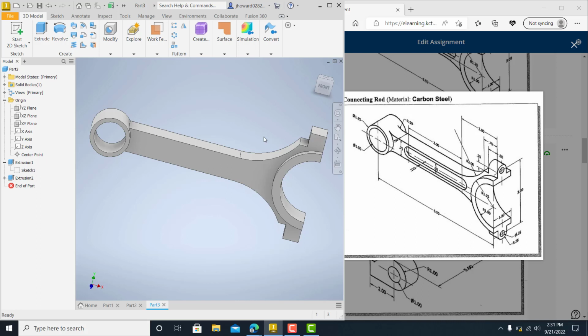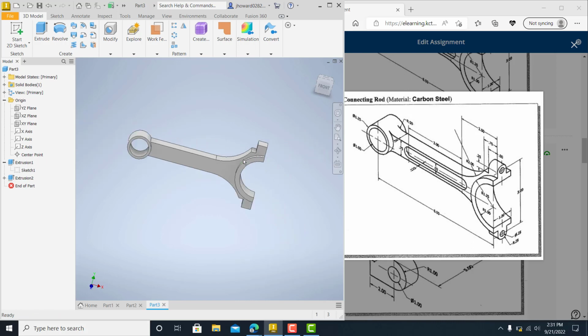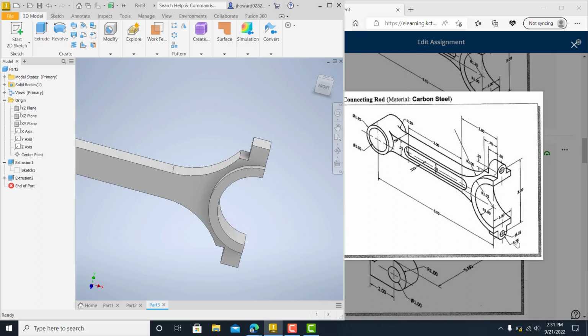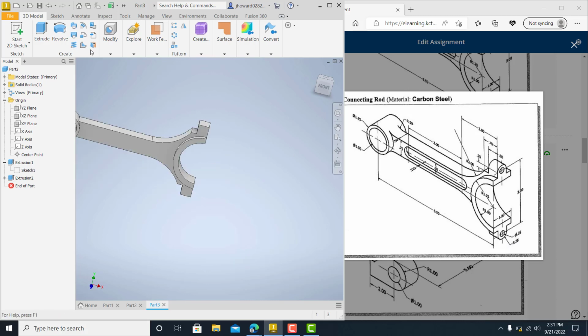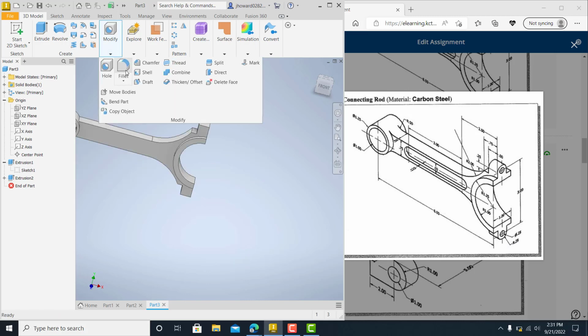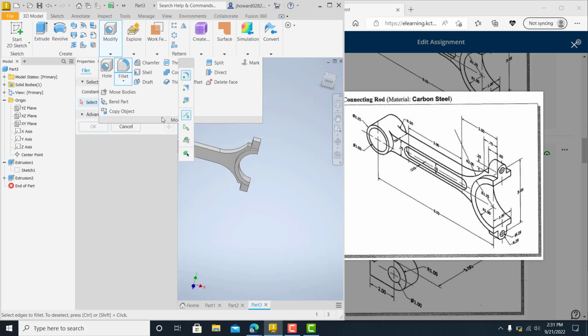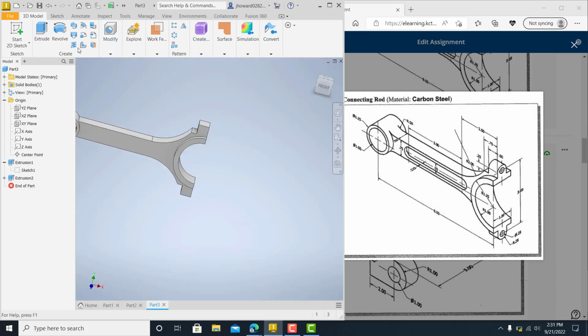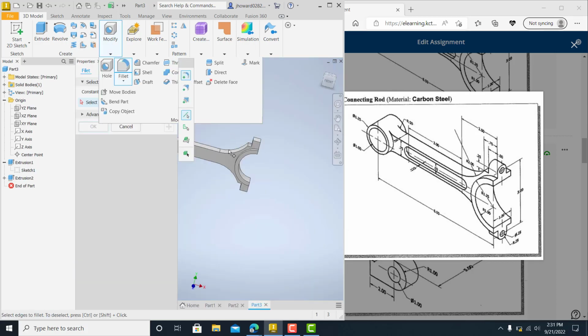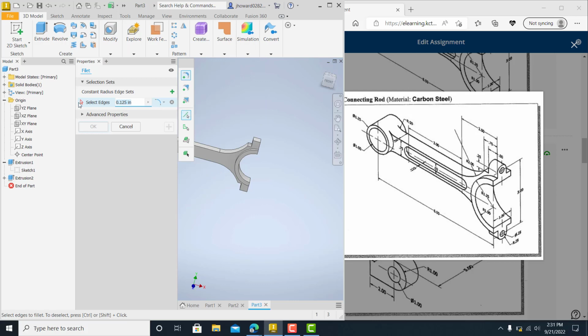And now when I go to line and bring that across to finish sketch, it'll automatically update it, made those larger. That's perfect. Because what I want to do here is I want to round these over. These are 0.25 radiuses, easy to do. Up here in modify, you got fillet, and inside that fillet should be 0.25. Okay, and you come in here, you click this one and this one, you rotate it over, you grab that one, and you grab that one.